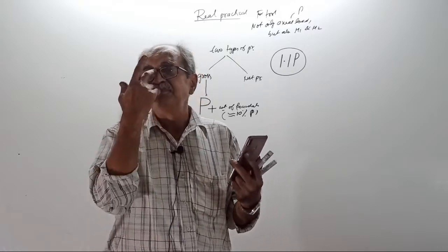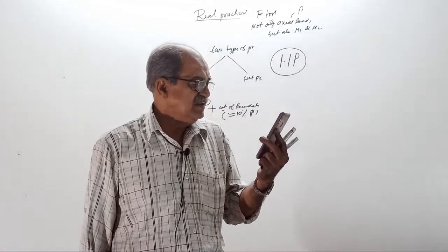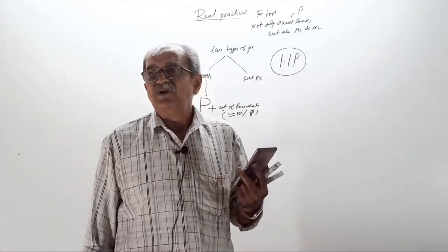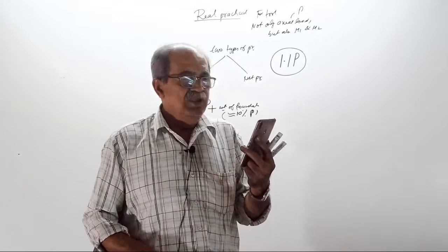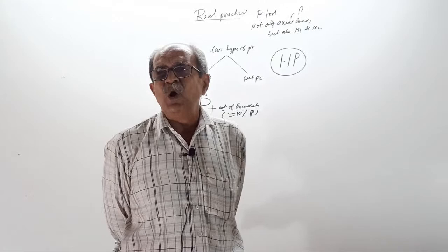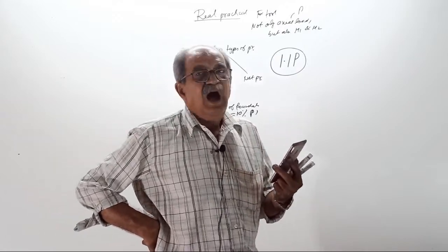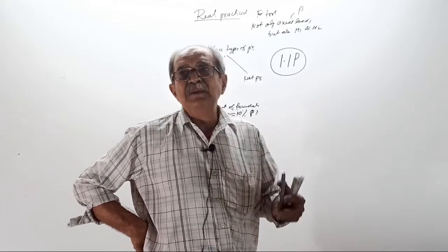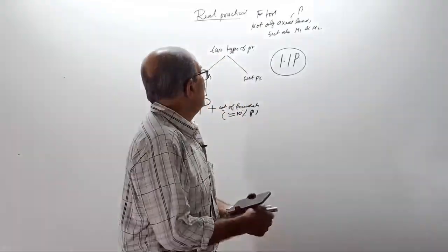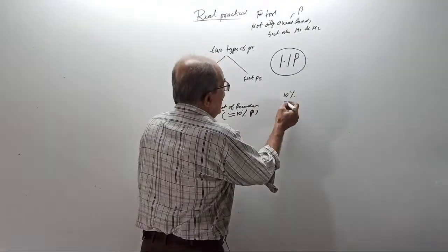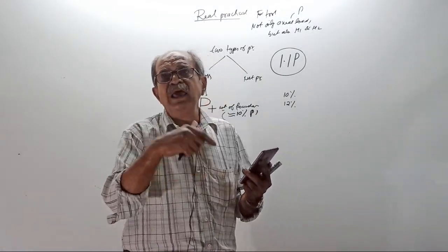In SAFE, do not assign 22%. Self weight it will calculate. Suppose you feel extra load is there, that whatever column load is there, 22% more is required. Do not assign 22%. Assign only 12%. Why? You decided that 10% is the self weight and the remaining 12% is extra. If you feel 10% self weight and another 12% extra is there, in the ETABS/SAFE model, assign only how much more?